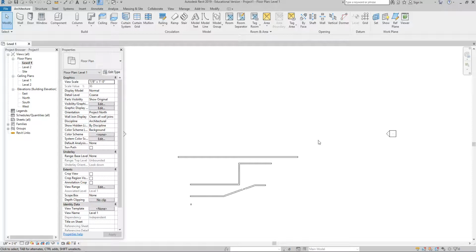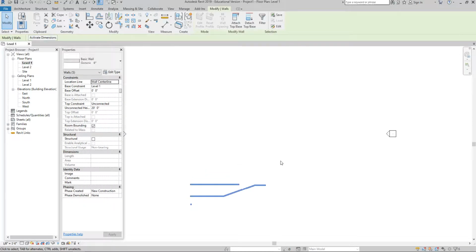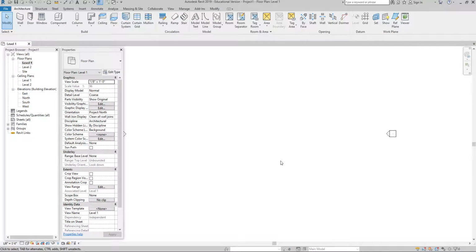I can also click, hold my mouse button, drag over the top of those objects, let go, hit delete. I can also click from this bottom left-hand corner, hold my mouse, drag up to the top right, let go, delete. Okay. Double click my middle roller and I zoom extent so that my entire drawing board is now back on the screen. All right.